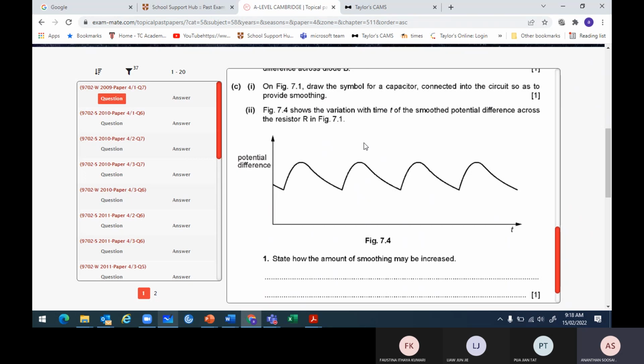Okay, the important thing is, of course, the ripple depth, right? We need to reduce it, so we increase the capacitance. So here it is charging. It's charging here. Here charging. In this case, here charging. So why do you need big capacitors? Why do you need big capacitors? You need a capacitance with a big value.